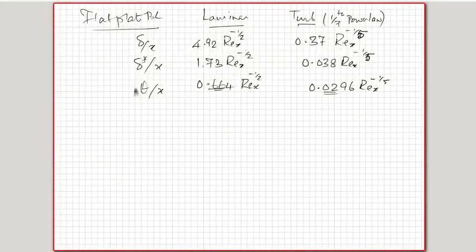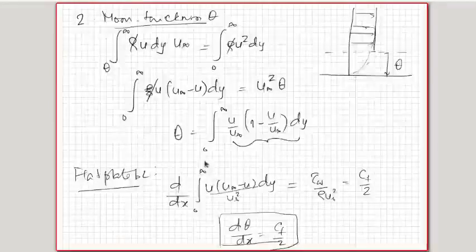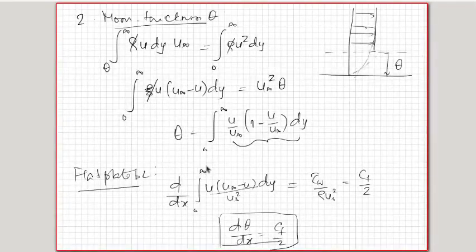Therefore, the moment any velocity profile is analytically given, or even assumed cubic or quadratic or half sine profiles, you can do the integral. The upper limit of the integral can also be written as delta notionally, but delta is understood to be where the velocity reaches the free stream velocity. That's why we write infinity in these definitions.